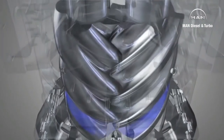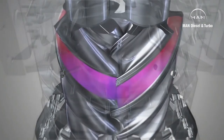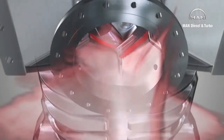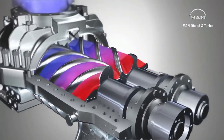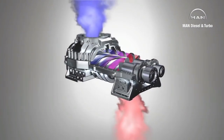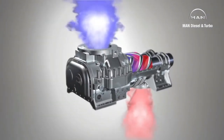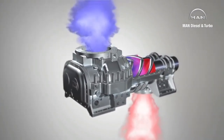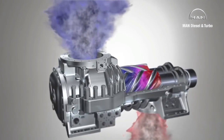Let's view the process again, this time from below. Once the gas is compressed, the chamber reaches another port connected to a discharge nozzle, and the gas flows out. In fact, all the chambers between the two rotors are being filled and emptied continuously. This means that with a screw compressor, the compression process is more or less ongoing.